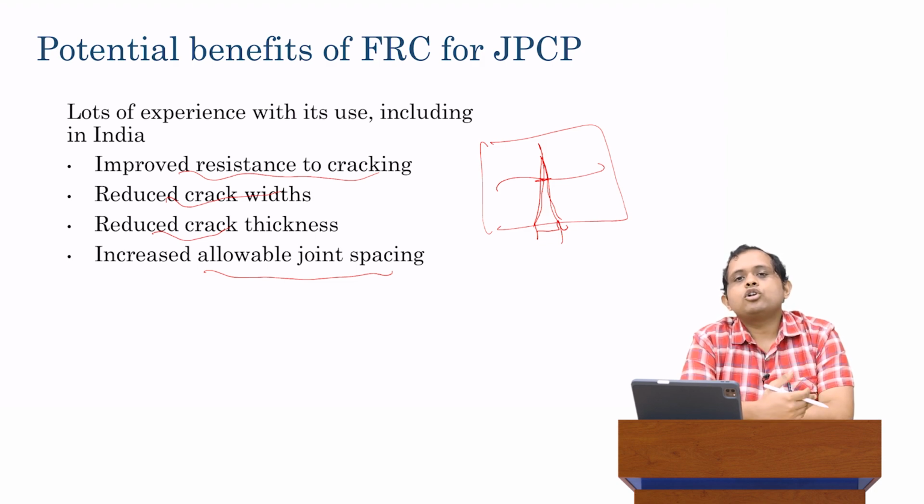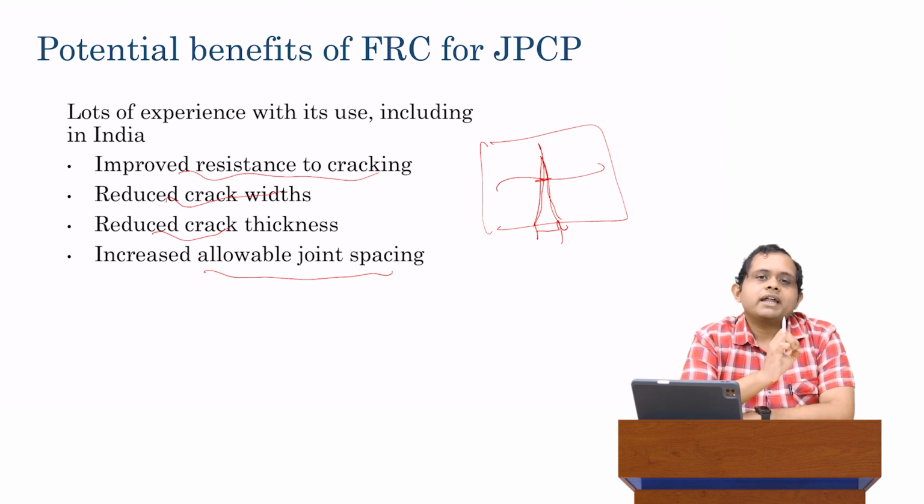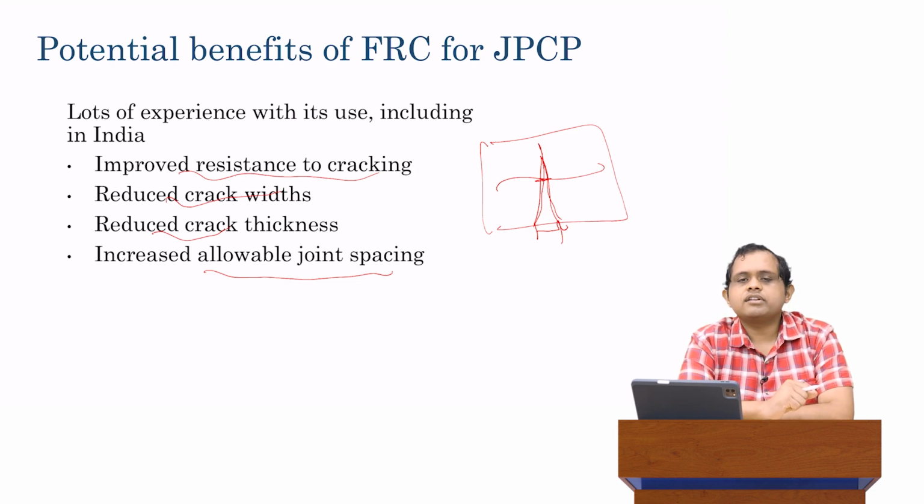Remember, if you have longer joint spacing, then effectively you're increasing the stress. If you're increasing the stress, you are going to start having more cracks. But if you can ensure that those cracks are small, that the crack width is small, you might be able to live with having more cracks. In which case, you can effectively increase your joint spacing because the cracks are not that detrimental to functionality as otherwise. So that's why you can increase the allowable joint spacing if you use FRC.